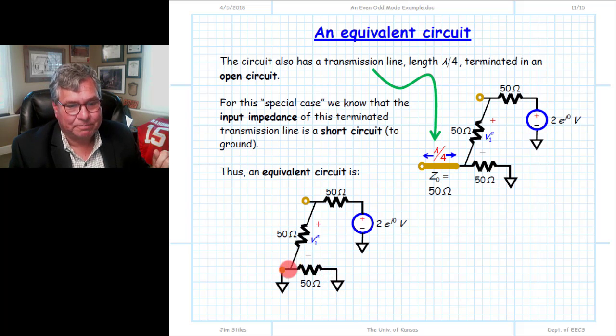There's no voltage drop from one side of the resistor to the other. And because the voltage is 0, the current through it is equal to 0. And really, this element becomes superfluous to the circuit itself. What we have is a voltage source followed by two 50 ohm resistors in series to ground. We simply can ignore this resistor in our analysis.